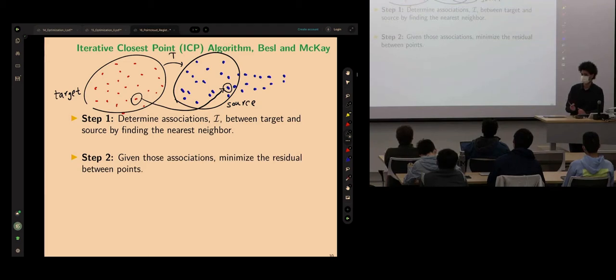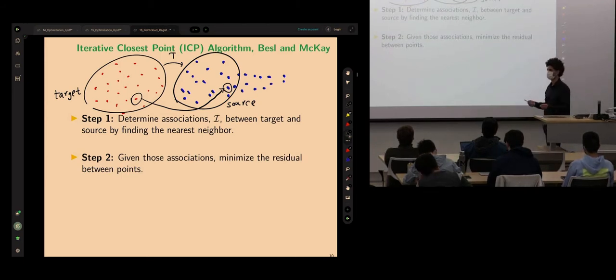Now, if you do not know that, how do you formulate a residual for the optimization to begin with? You do not know how to define a distance metric. You can only calculate the distance between two objects that you know you want to measure the distance between. The sensor will not tell you this. The sensor only gives you a point cloud. You move, you have another point cloud.